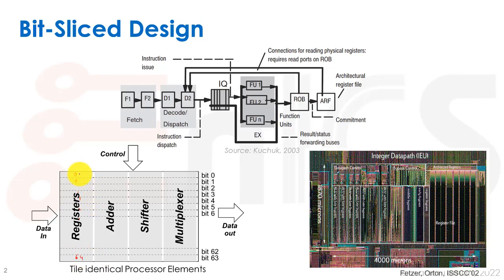Then we drive out the bits on wires that go horizontally along the whole ALU. We can put different units over here, such as one adder, two adders, a shifter, a multiplexer, and different types of things. Then we just tap these bits to get their inputs and drive their outputs, and we get the data out, the 64 bits out. That makes our lines really nicely forwarded together.